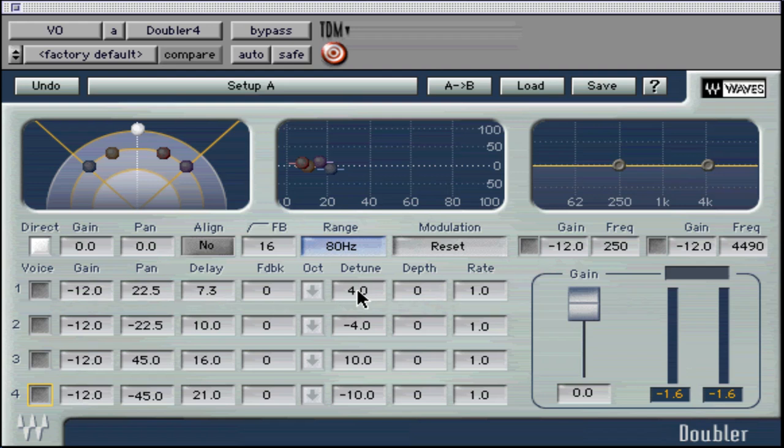I remember using various signal processors to double vocals in the late 1980s, essentially to thicken and widen the lead or backing vocal tracks. The difference with this and Doubler is that Doubler preserves audio duration when changing the pitch of the doubled signal. This replica is decorrelated by the initial detuning and the pitch can be further modulated. The end result is the effect of a doubled take rather than a signal mixed with a modulated version of the original track.